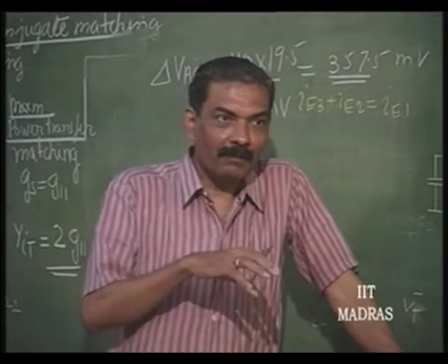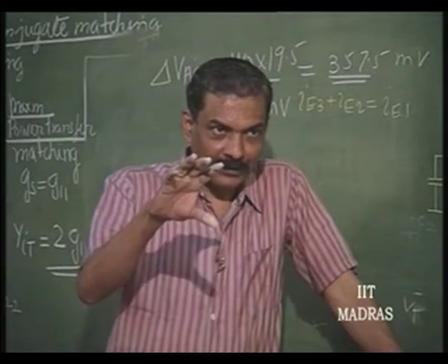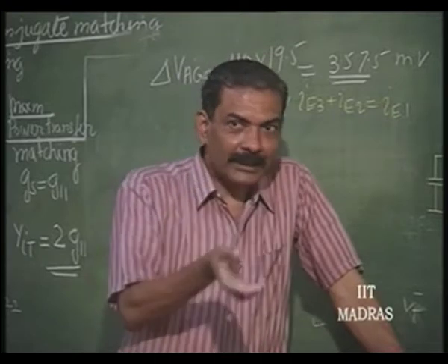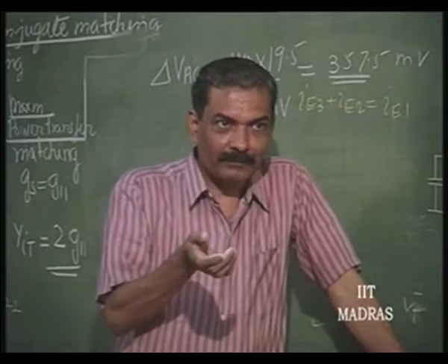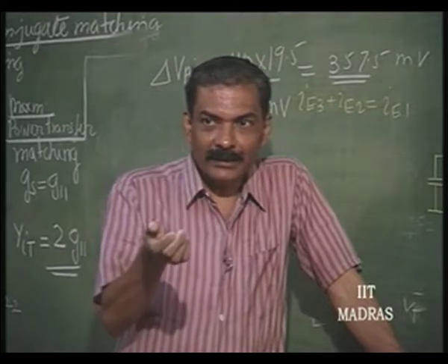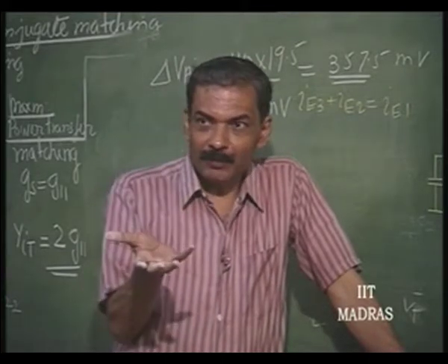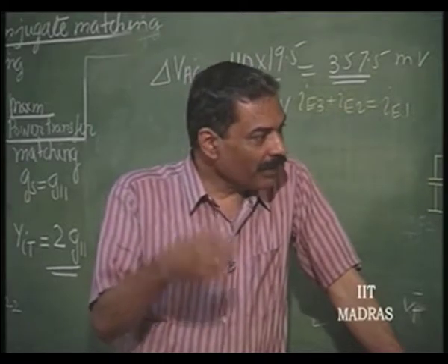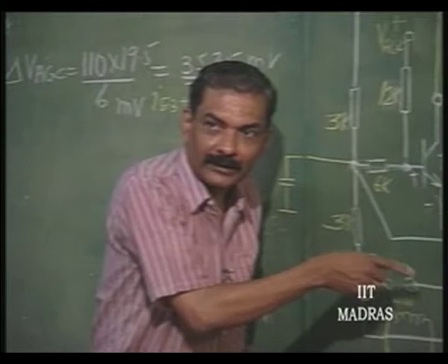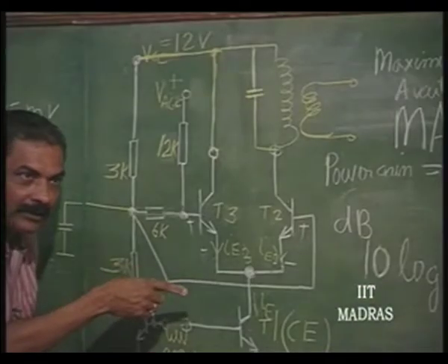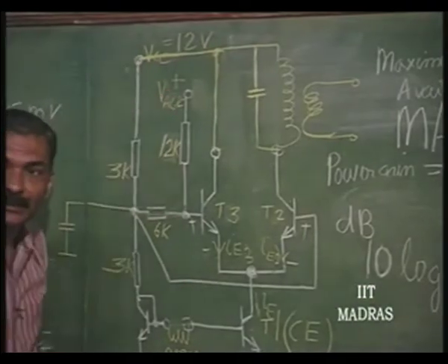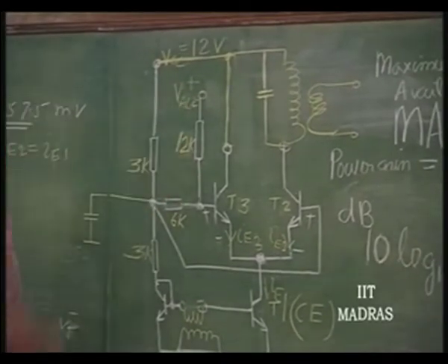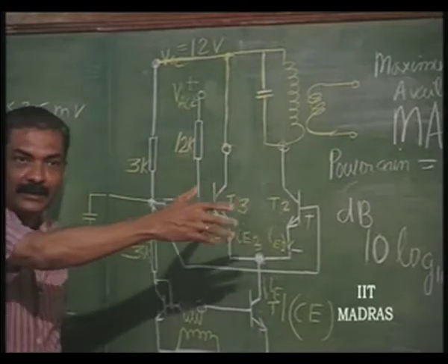This should be done by finding out what the IF gain should be. So, that can be found out from measuring the IF amplitude itself. So, in the detector you can actually get a DC proportional to the IF amplitude, okay, and that DC is made to control this current, okay, division here, that is this VAGC. That DC that you obtain at the detector is the VAGC, which will control all the gains of the IF stages as well as the RF stage.